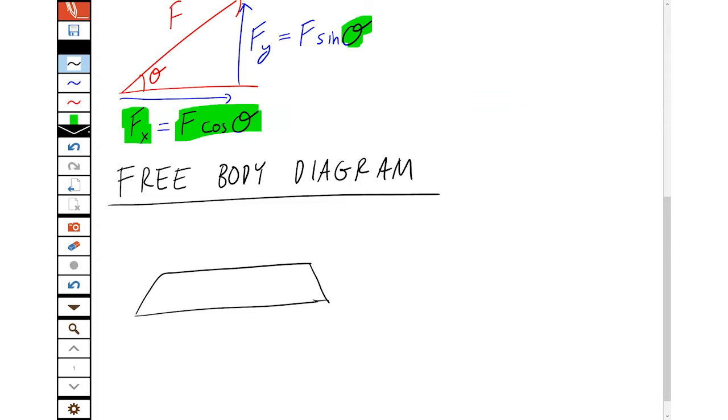So if we then have some forces acting on that, so let's say we have 200 newtons pushing to the right. We have the force A at 45 degrees like that, and we have the force B pushing down. Now you'll notice here something about the forces. It doesn't matter where on the body the forces are. As long as they're on the body at all, you can add them up like this. And so we're going to go through this. We draw our little axes, so we remember which way is which. Y is up positive, X is to the right positive.